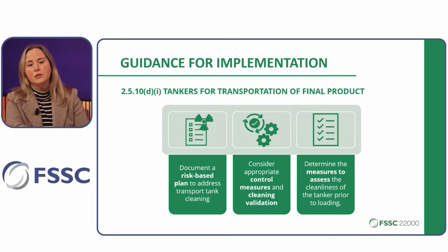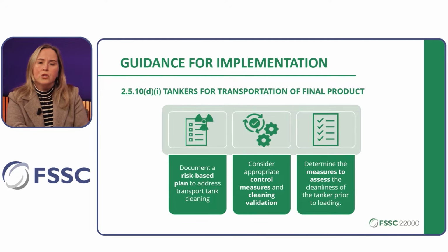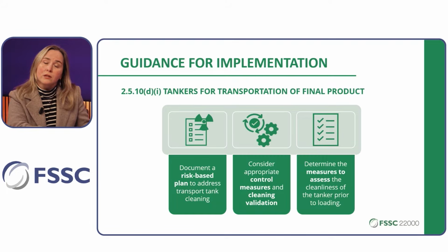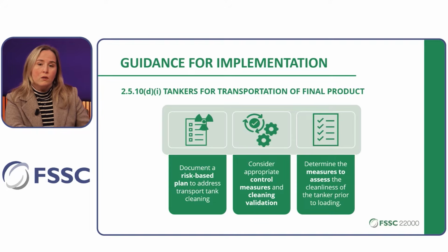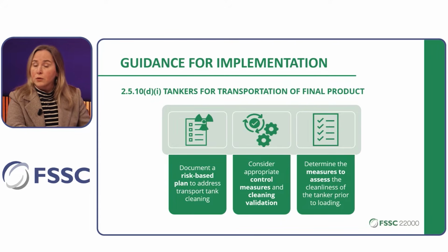The organization needs to determine the measures to also assess the cleanliness of the tanker prior to loading, and this may include a verification checklist or a similar document being in place and assessed against the specification that is being set for those cleaning services. So depending on the risk, this can vary from visual checks to the verification of the cleaning process data, as well as microbiological testing. And this verification would need to be done at a frequency based on the outcome of the risk assessment that the organization has undertaken.